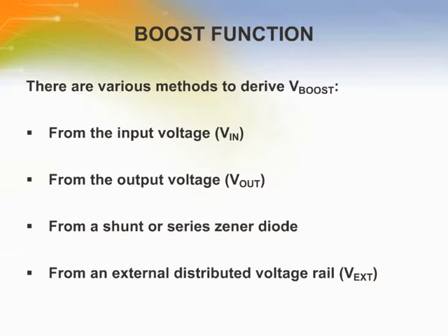To properly drive the internal NMOS switch during its on time, VBoost needs to be at least 2.5 volts greater than VSW. A large value of VBoost minus VSW is recommended to achieve better efficiency by minimizing both the internal switch on resistance, RDS(on), and the switch rise and fall times. However, VBoost minus VSW should not exceed the maximum operating limit of 5.5 volts.